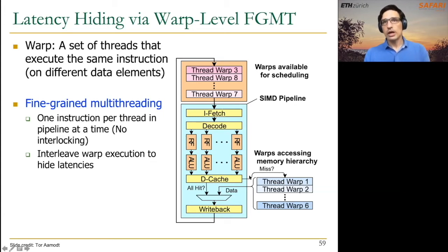The other part of the cache is what is called a scratchpad, also called a kind of software cache, which means that the programmer himself or herself can decide what's going to be written into this cache for faster access. Because when we have caches in the pipeline, their access is much faster than going to the large DRAM memory that we have outside of the chip.